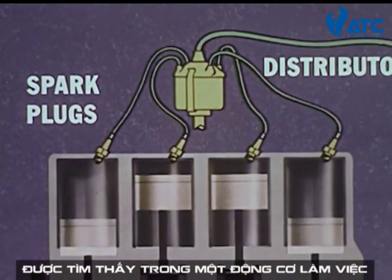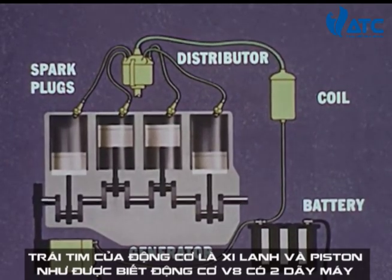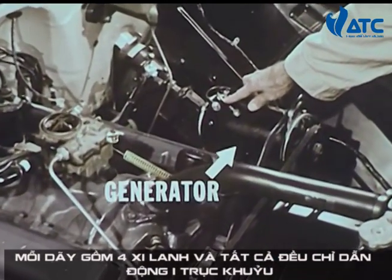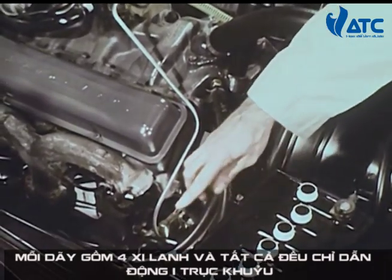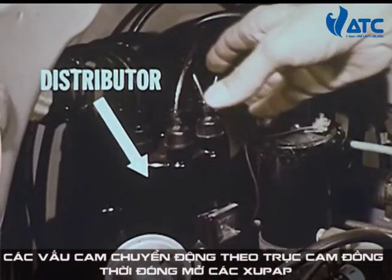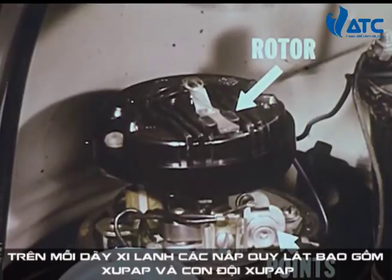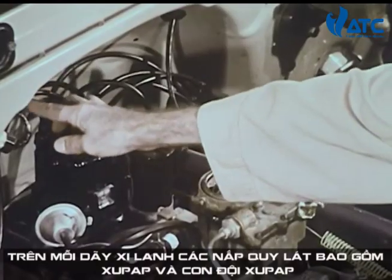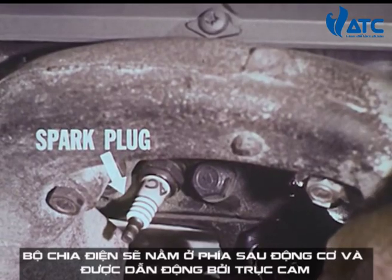Here again are the major parts of the engine's electrical system: the generator, the battery, the booster coil, distributor, and spark plugs. Now looking at an actual engine, here is the generator and the battery. Together at the rear of the engine are the coil, the distributor cap containing the contact swept by the rotor itself, and the points which sometimes need adjustments. And finally, in the cylinder heads, the spark plugs.